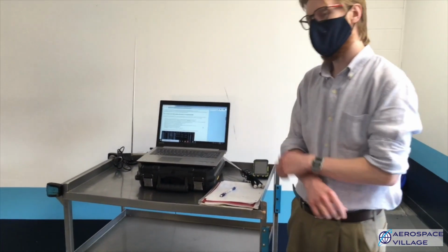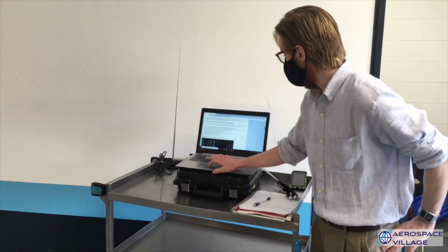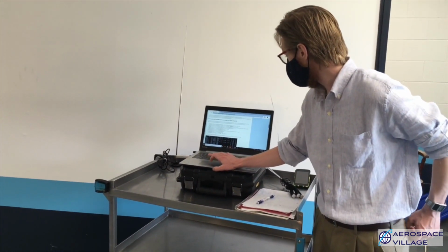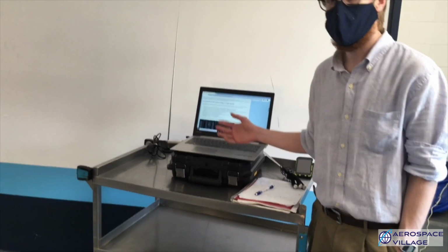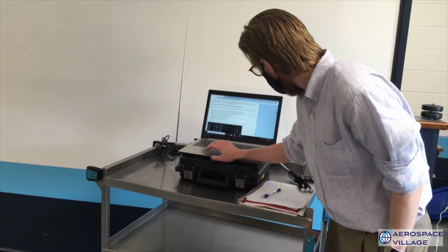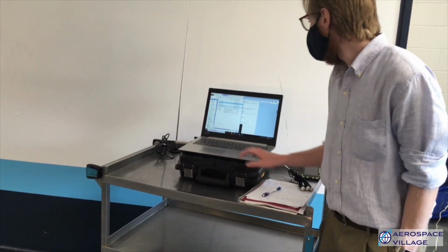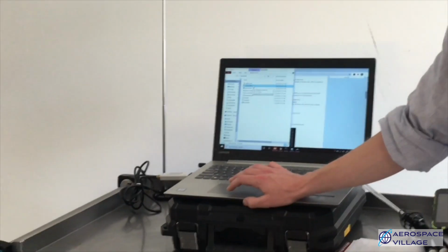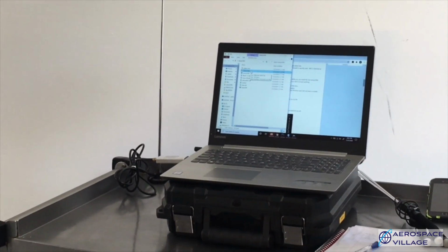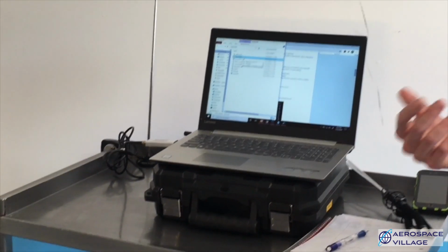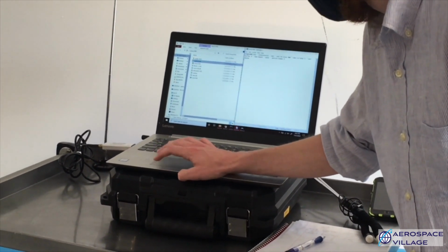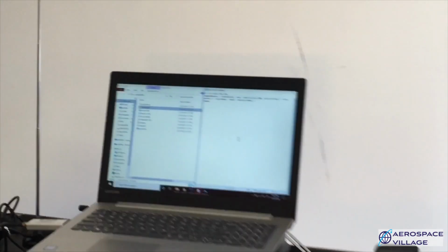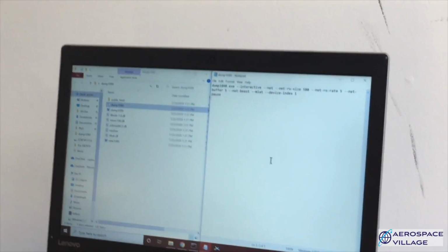First we're going to install a program called Dump1090, and this program is available on pbworks.com. Once we have it installed, we'll get a zip file and extract that. There, the first thing that we will run is the Dump1090 batch file. If you have any trouble with it, or if your computer says that you have multiple devices, you can add a parameter that will allow you to select that device. Device index.